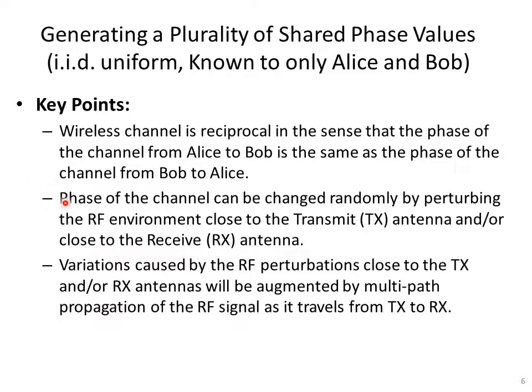First, dealing with the fact that we need many of such shared phase values. This can be done because the phase of a communication channel is composed of the phase from the transmit antenna, including the immediate neighborhood, the near field of the transmit antenna, to the receive antenna, immediate neighborhood and near field of the receive antenna.